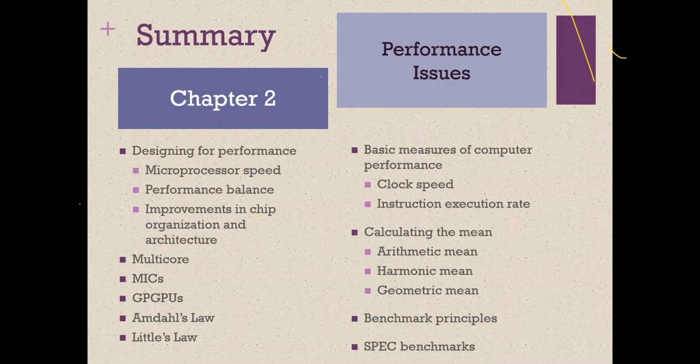If there is, it will deal with that like a loop back or a feedback. And so then that interrupt request is now going to be fetched within the fetch cycle and then executed within the execution cycle. And then it goes back to check again on the interrupt and so on and so forth. So that redefines the instruction cycle for us. So when we talk about the stages, that's what we mean.